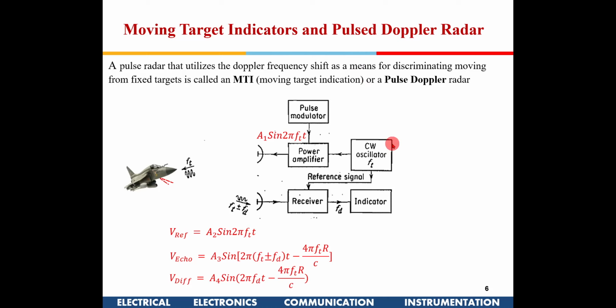Using the normal pulse range equations, you find the range. Over and above that, along with the time which is noted between the transmitting and the received signal, which is used to compute the range, we also are going to measure the Doppler shift in the received signal, and based on that Doppler shift, we are going to say that it's a moving target or it's a fixed target.